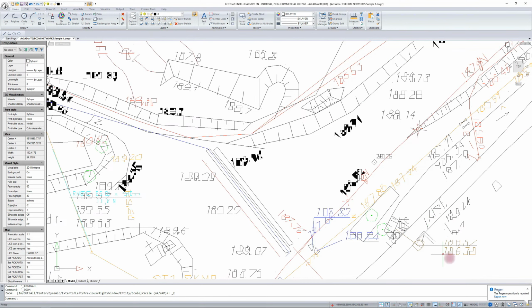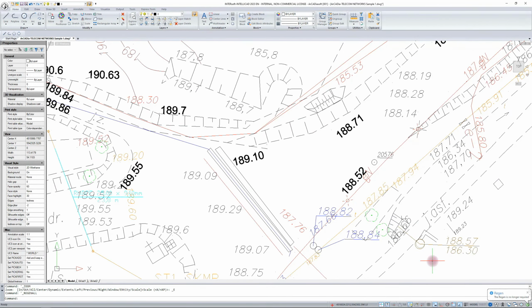It happens very often that we open a drawing just with a map, zoom in on a part of it, and suddenly, horror, what happened? The project has messed up for us. Something is happening? No, it's just that the drawing has not been refreshed. We can click here at the bottom of Regen and choose this option from the View ribbon under Redraw. But I have a keyboard shortcut defined, and I won't hesitate to use it right now. I press F5 and the program redraws my view.